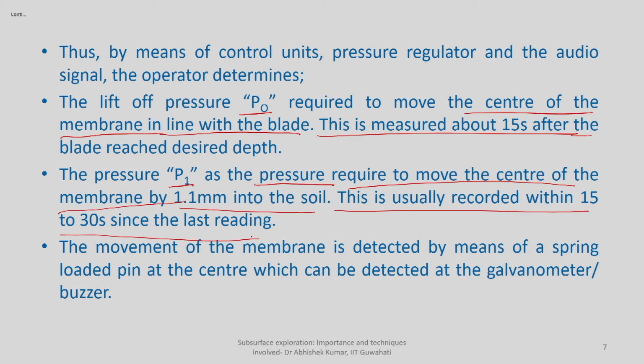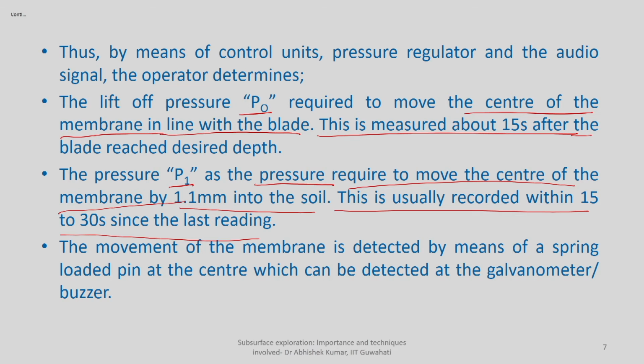Last recording means that you recorded the P0 value, after that you started pushing the membrane into the soil, and then maybe 15 to 30 seconds it will take, depending upon the depth and accordingly how much pressure you have applied. So you apply that pressure for 15 to 30 seconds and then measure the value of P1. Of course, there will be pressure gauges at the surface which help you get the pressure you have applied, whether for inflating or deflating the membrane.